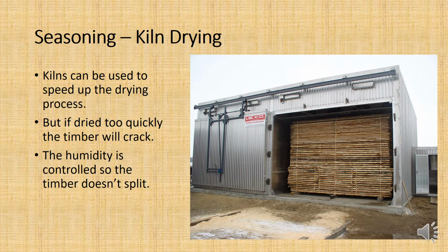Now, normally with kiln drying for timber, you would raise the temperature to, I would say, about 40 to 50 degrees Celsius. That's probably as hot as it goes. Usually it's about 40 degrees, I would say. So it's not really that much hotter than Kurdistan on a hot summer's day.